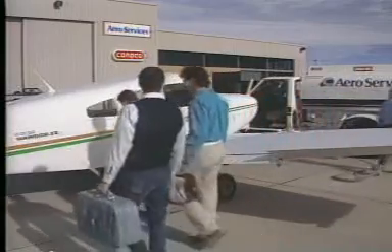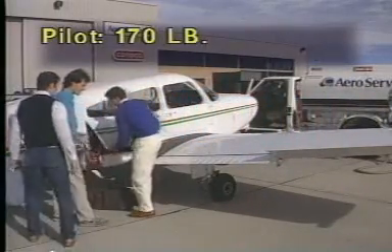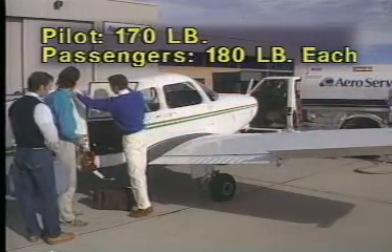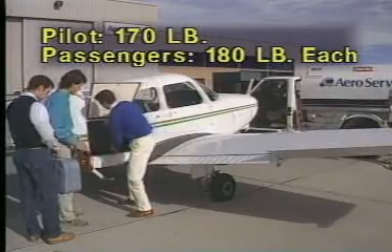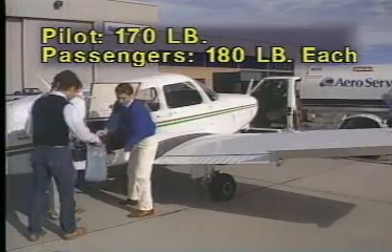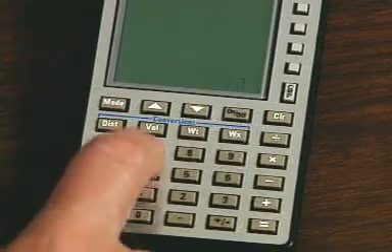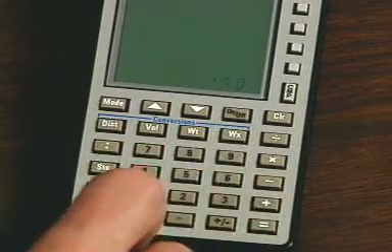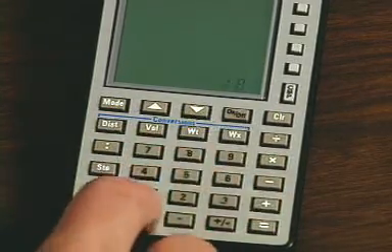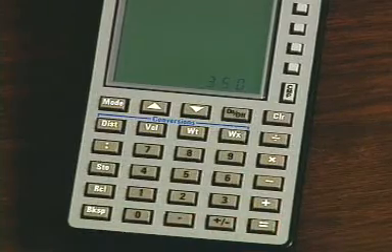You must then complete the weights and moments for the rest of the useful load. As a sample problem, assume you weigh 170 pounds and you're going to be carrying 2 passengers who each weigh 180 pounds. Since one of the passengers will be sitting in the co-pilot seat, you need to add your weight to that of the passenger. The result is 350 pounds.